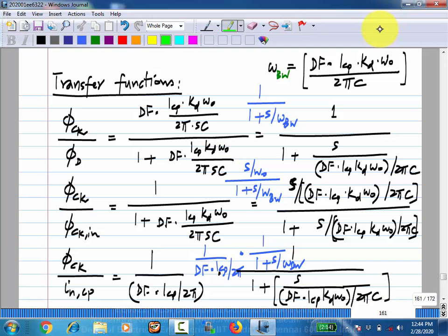So that is the usual circuit scaling, right? You can make a low pass filter with a large R and a small C, or a small R and a large C. The difference between them, for the same bandwidth, will be noise. Okay. So based on that you can calculate these things.